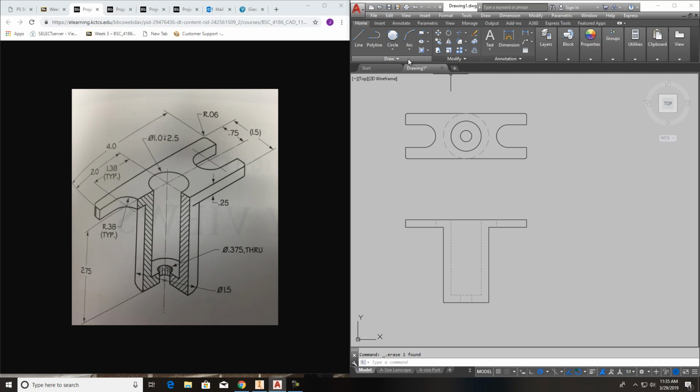But now on a half section, you would go from there, and then you'd have a line right here. And this would be your cutting plane, and then this would be the piece that you pull out. And then when this thing turns and comes down to the front view, you're only going to see half of the section. That's why it's called a section view. Even though you're pulling out a quarter of it, when you turn this thing over, you're seeing half of that part, its internal parts of it.